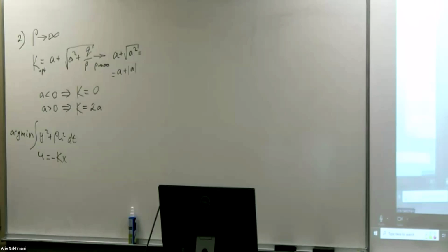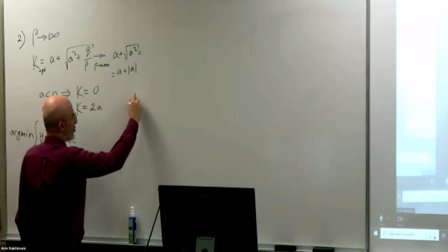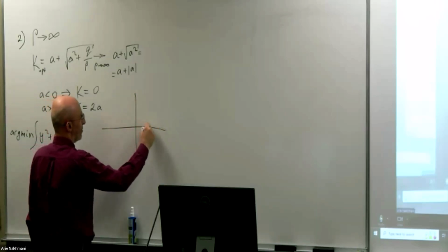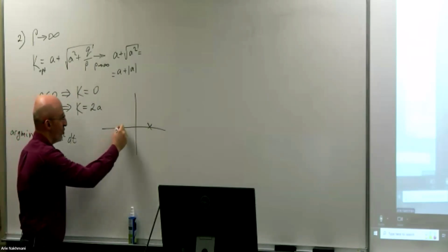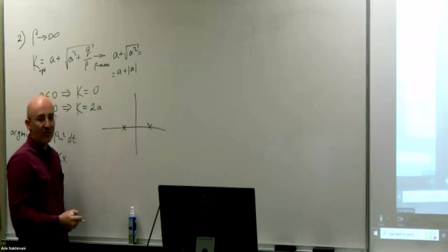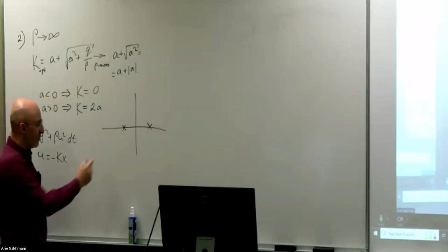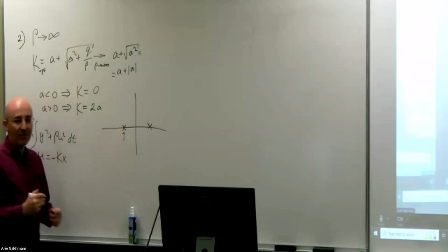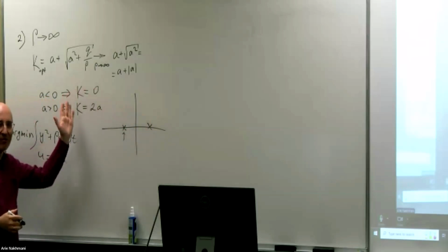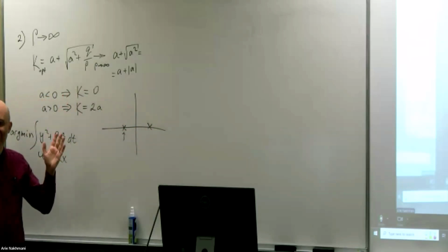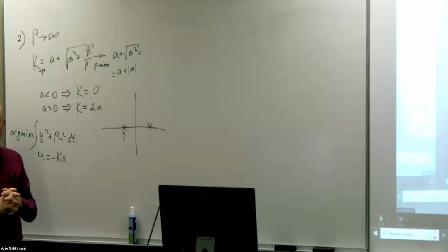for that case? Let's say your symmetrical root locus, your open loop is like that. This is your open loop. So how would your symmetrical root locus look? It will be a mirror image. So it will jump here, just a mirror image. And this will be your optimal one. Which means whatever the unstable poles here, you will just reflect them here, and that is your answer for rho goes to infinity. Let's see if this is what happens here.